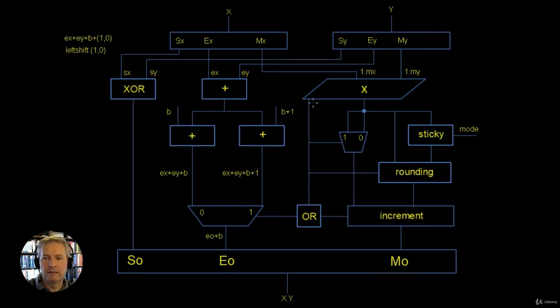And that choice will be made by the 48th bit. So again, we're going to have a look at this before the end of the video in the VBA example using our multiplication tool, and we'll talk through it with respect to that, and it'll become quite clear what we're doing here. So that output then, this point here, is the actual 23-bit output of the mantissa, and it's starting at the right point, so either starting at the original decimal point or the decimal point one place to the left.